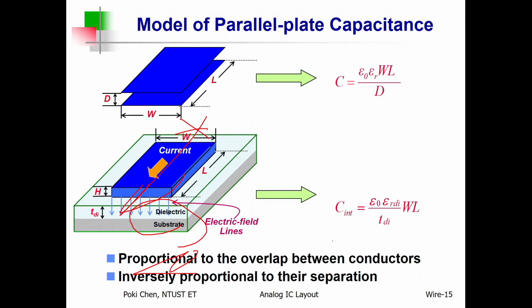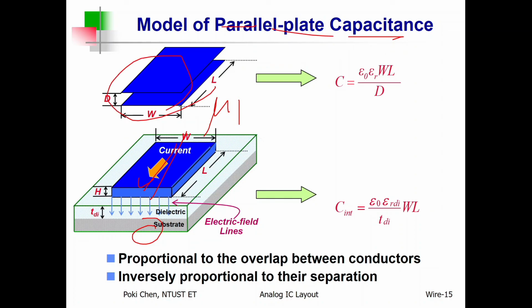I would like to say, even though you don't have the other layers below it, then below the wire, especially the metal one, for example, you have substrate, and then there will be some kind of parasitic capacitance between the wire and the substrate. According to the definition for the so-called parallel plate capacitance, just look like this. If they are two plates, conductive, and in between you have some kind of insulator. For the insulator, it has such kind of epsilon, right? The dielectric constant. Then you will see the overall capacitance equals the epsilon, the overlap area by the distance between them.